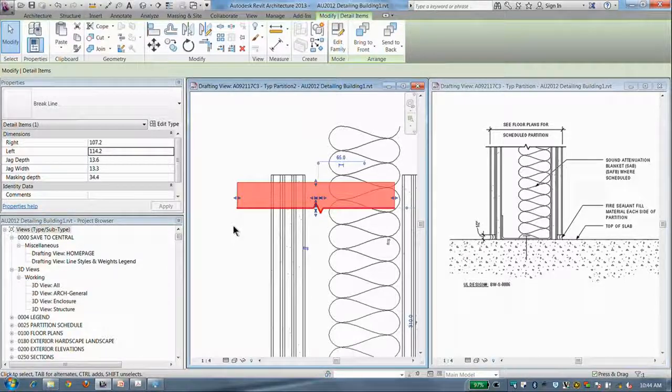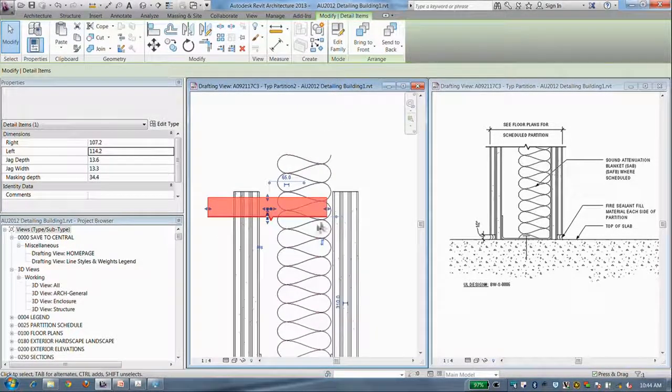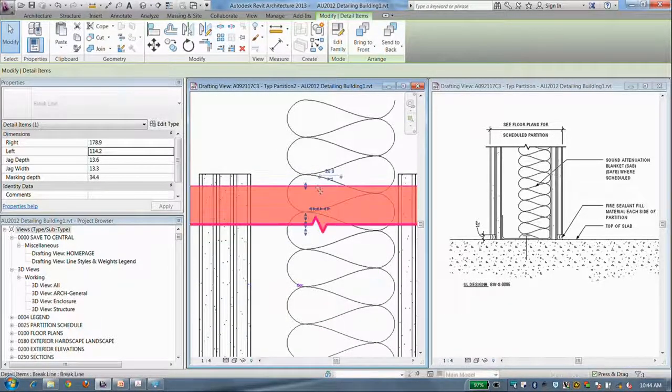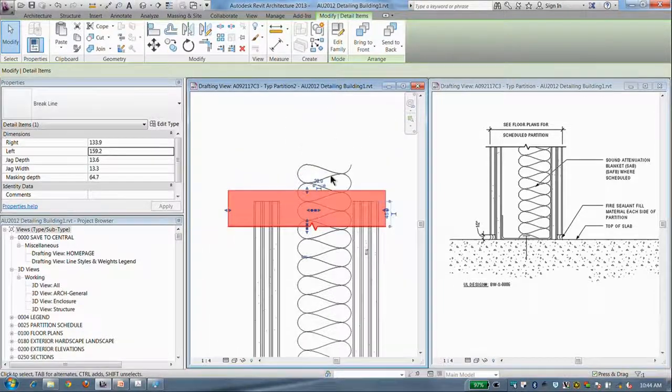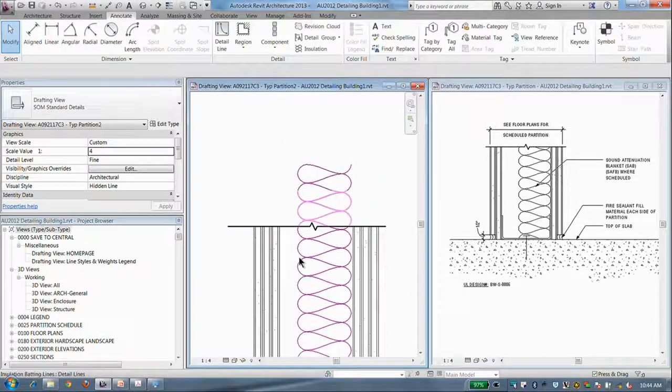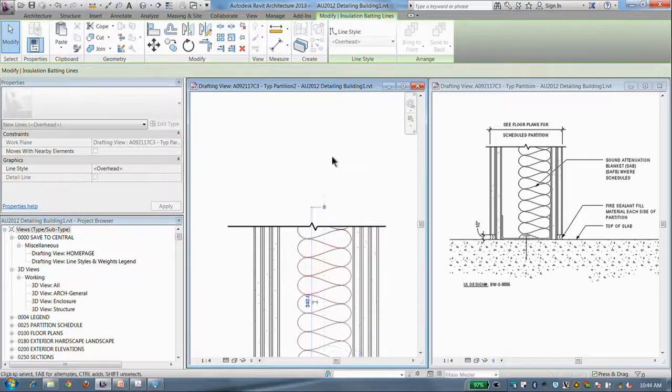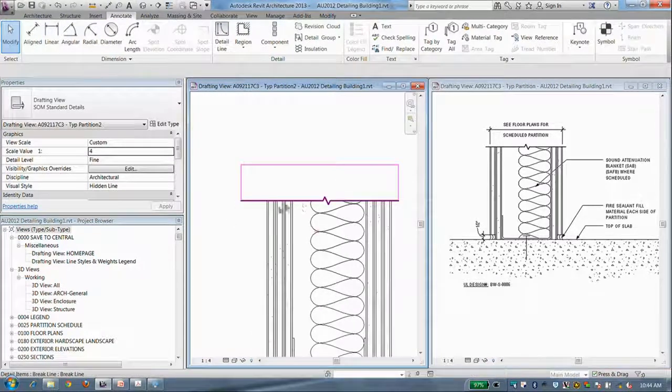In Revit, model geometry, if you're not in a drafting view, if you're in a regular view, is always in the back. Detail components, details, and so forth are in the middle, and annotations are on top. So things like arrows, text and text itself, level lines, structural grid lines, those are always on top. Here we can actually come in and grab the controls and adjust these parts. And let's actually grab this and move this down, so it just obscures the stuff that's behind.